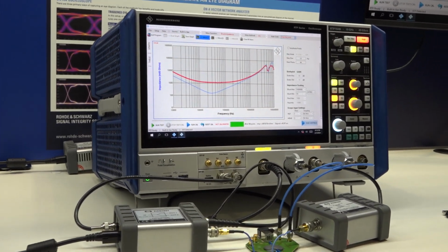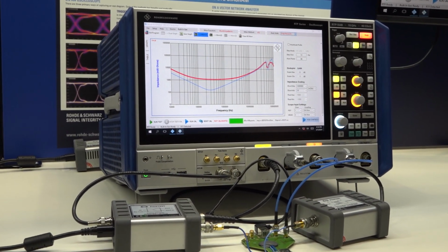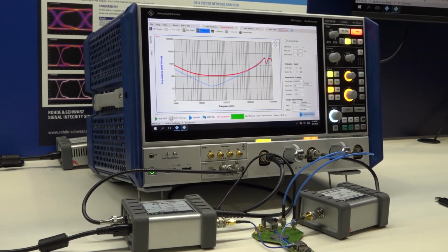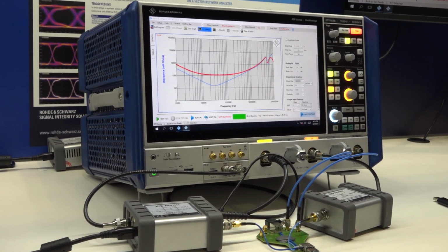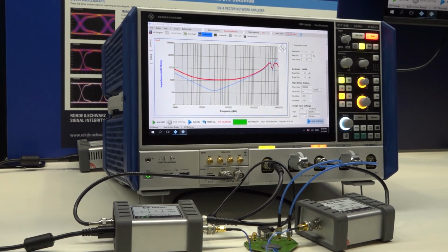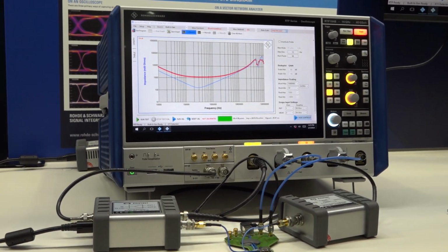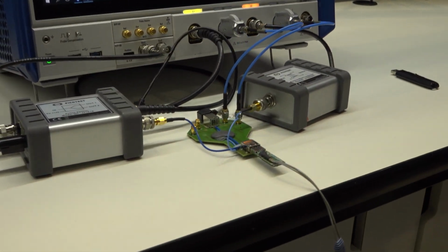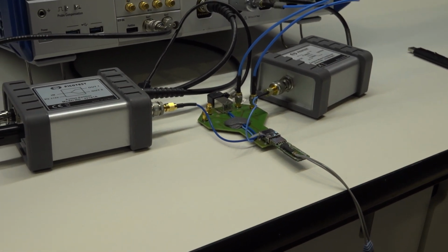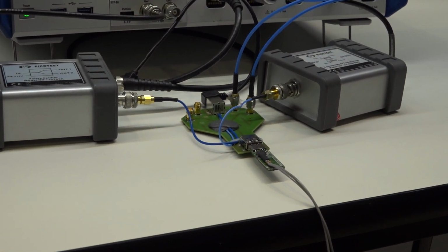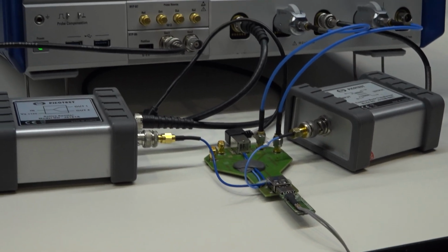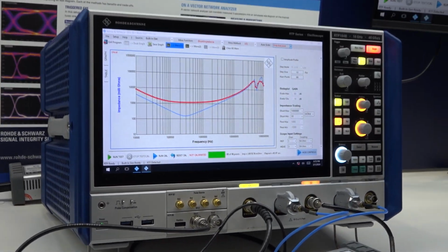So we've actually been able to correlate the problem with the power distribution network and the result that we had on the jitter, and even bring it down to the specific component that's causing the problem, in this case the capacitor. I think a better capacitor would provide more noise rejection in this case. Not to say the drive's not working, but it could be better with the right power distribution network.